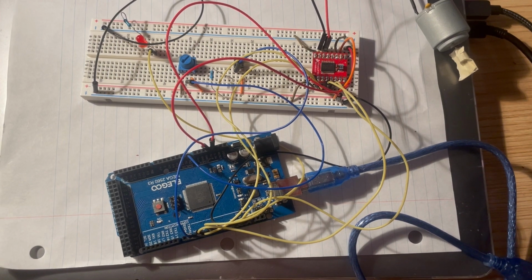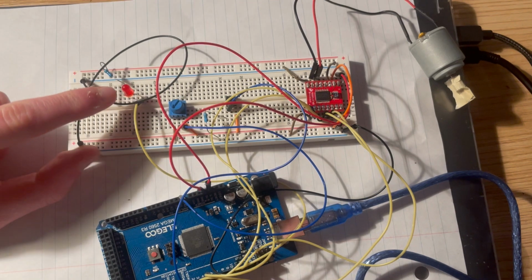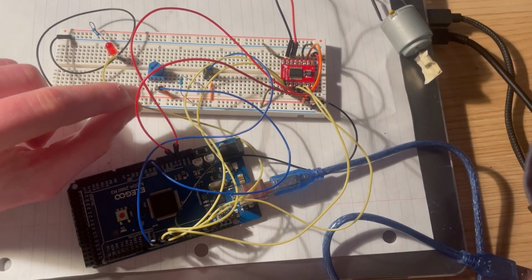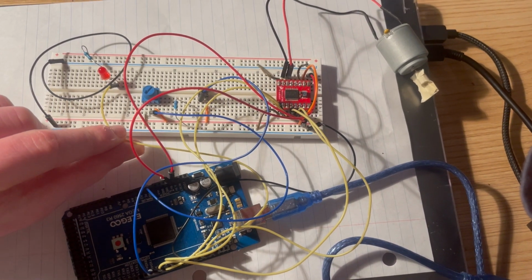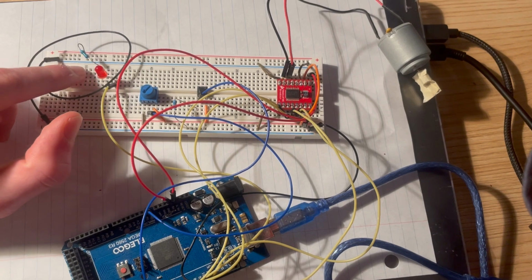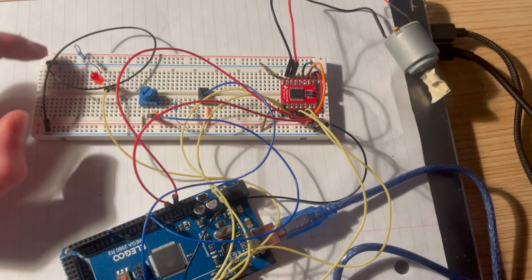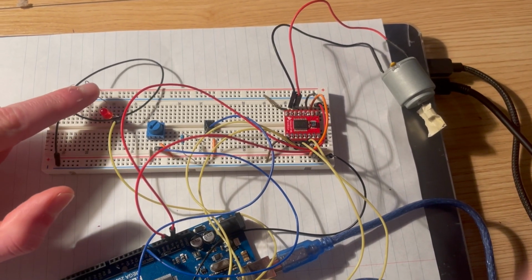I'll also show you how the rest of my project is wired. So starting with the LED, we have that wired from a digital output on the board, and then the code will tell it when it's on and when it's off. And then we got a 100 ohm resistor grounding it to complete the circuit in this ground strip, which in turn goes back into the board. The resistor is just to protect the LED.